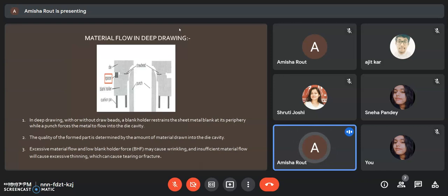Addressing these difficulties requires a good understanding of metal flow and how it is affected by draw beads, step beads and drawbars, as well as the effects of part geometry. All too often, draw beads are used in an attempt to obtain stretch and reduce wrinkling when the basic part shape is not conducive to stretch and could be altered without affecting fit or function. Successful stretch can be obtained through the use of draw beads, drawbars and changes in part and addendum geometry.